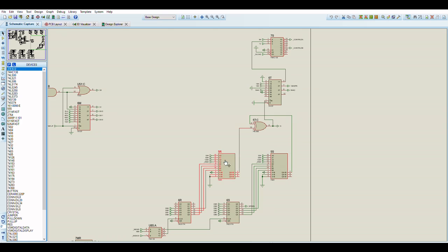These are the two comparators, and based on the output from the comparators, it would subtly tweak whether or not you were using 16 or 32 pixels. It meant that when you started rendering the 32 wide sprites, you would effectively reduce the number of sprites that were displayed for that portion by 2, but double their horizontal sizes.